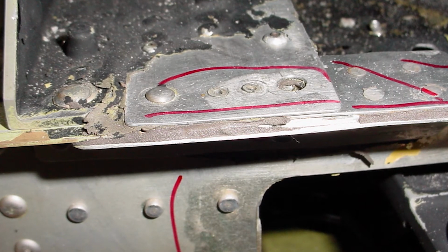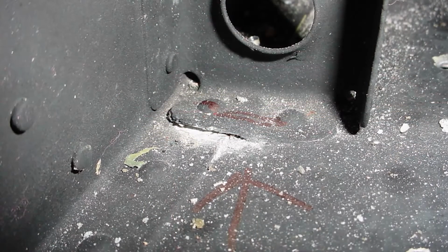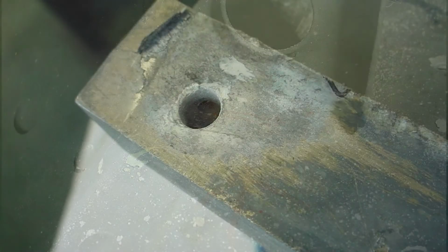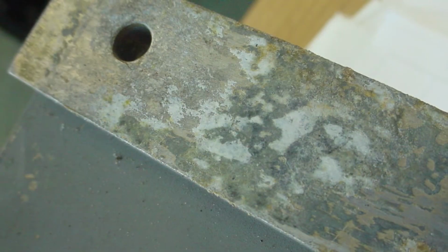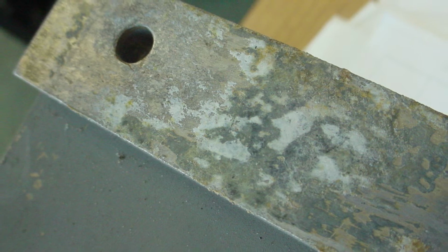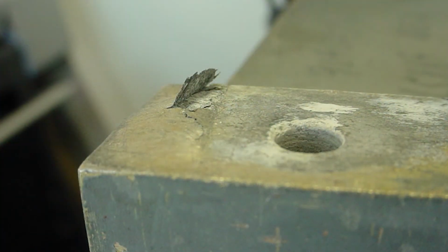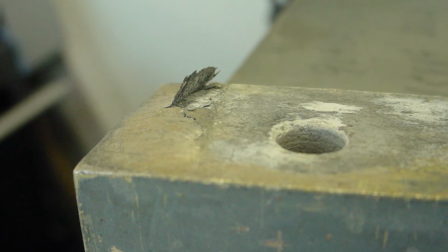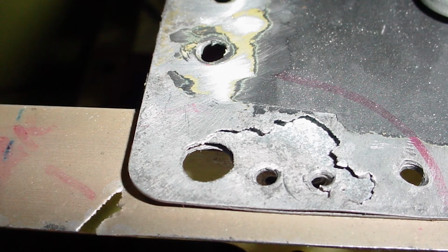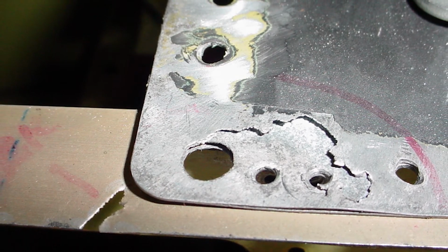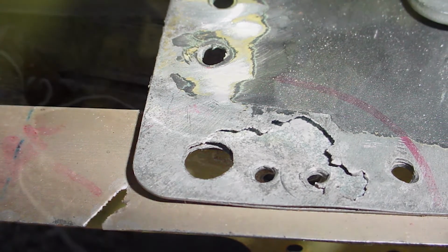Pitting corrosion is the most common type of corrosion found on aluminum alloys. Here you see an example of light corrosion which shows minor pitting and discoloration. The first indication of pitting is a gray or white deposit. When the deposit is cleared away, tiny holes or pits are evident. Moderate corrosion may show evidence of flaking and scaling, along with some paint blisters. Severe corrosion includes many of the same characteristics seen in moderate corrosion, but intergranular corrosion and exfoliation are also present.